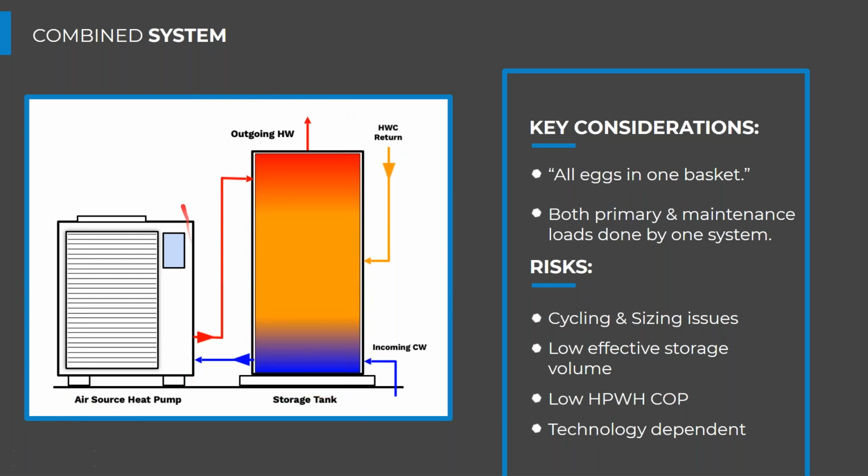Use 2 or 3 heat pumps instead of 1, so that you can better match and only bring on 1 heat pump to reheat the hot water circulation return losses, and then bring on the rest for the full primary heating load. Staging is critical in combined system designs to mitigate the cycling issues related to the difference in scale between our heat loads, whether temperature maintenance or primary heating, people actually using water.